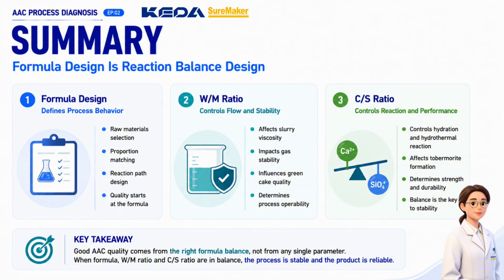A reasonable formula design is not simply a proportion of raw materials. It should ensure that gas generation and thickening are matched, hydration and hydrothermal reaction are matched with the production rhythm, and the final product after autoclaving matches the design target.